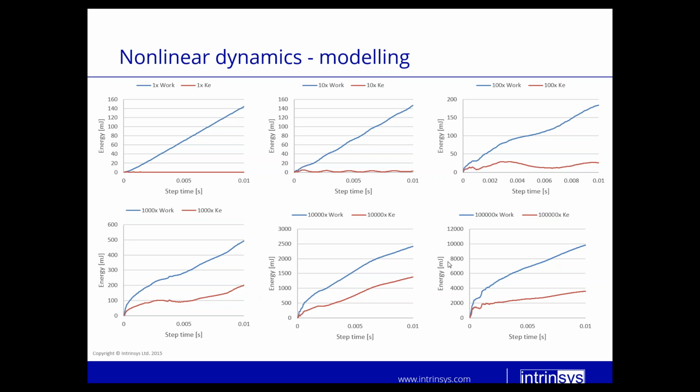So based on this, if you had to choose, you either have to choose real time, or you can go up to maybe 10 times with mass scaling. This obviously takes 10 times less. Now you can ask the question, why would you want to increase your time increment 100,000 times? But if you think about it, if some of your elements, as we see in a 1 millimeter element, would have a 1e-7 time increment.